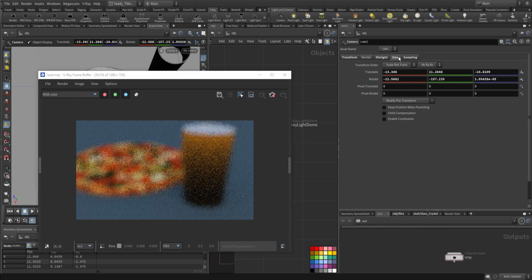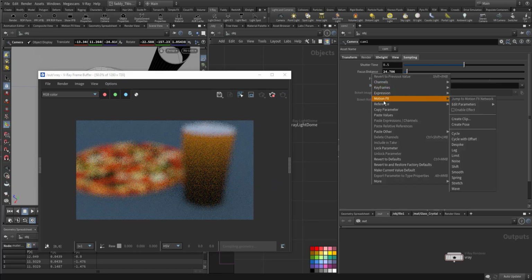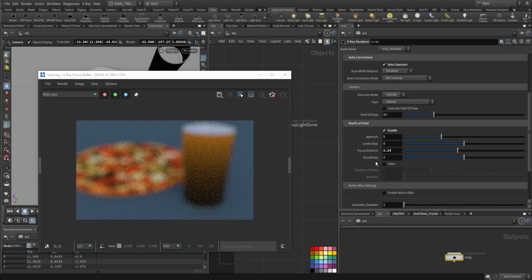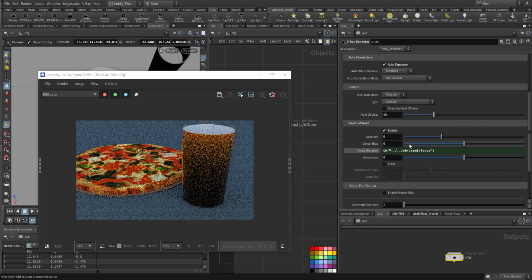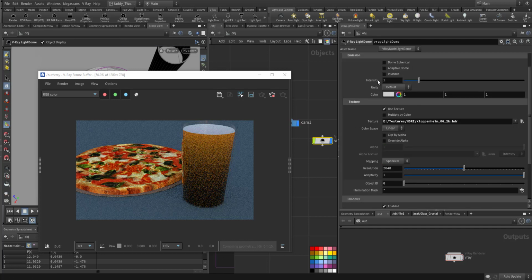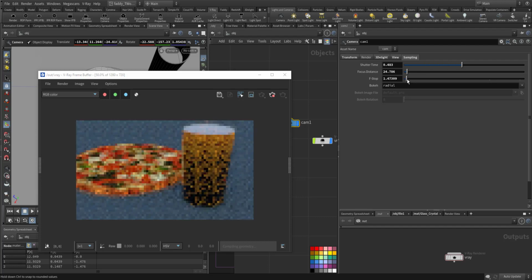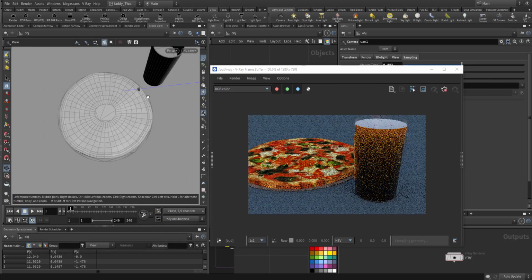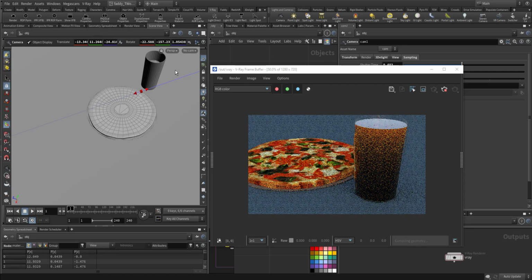Then what you do in the view sampling, focus distance, copy, you go to the V-Ray, focus distance, paste relative reference. So it's connected now with the camera here. Shutter, you can play with the shutter, the f-stop, it's very tiny, or you can control it through the interface here. Make it very small slice.